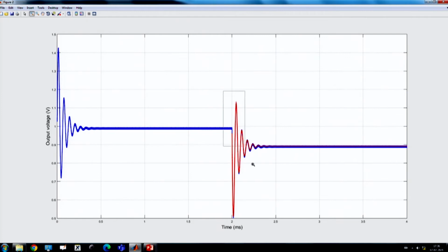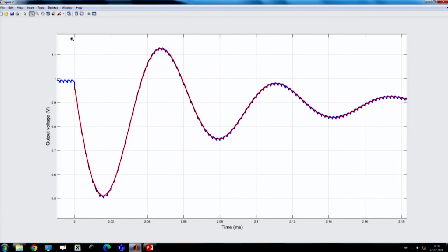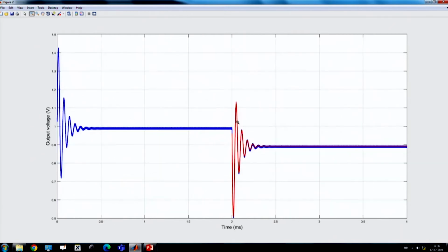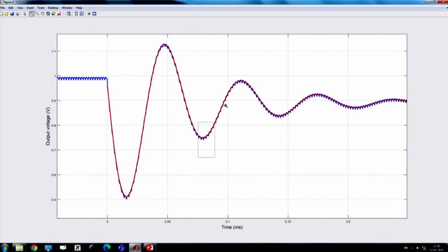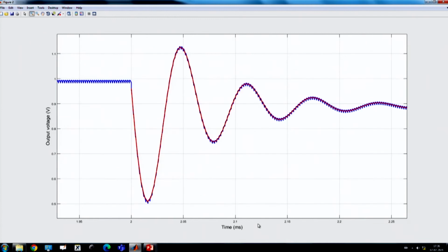And if you check the transient response, that means load transient response for an open loop converter, you see that our AC model, small signal model, is perfectly capturing the actual switch simulation. All these models are perfectly captured. That means, for load transient response, our model is perfect.